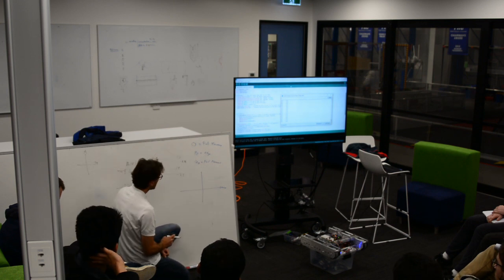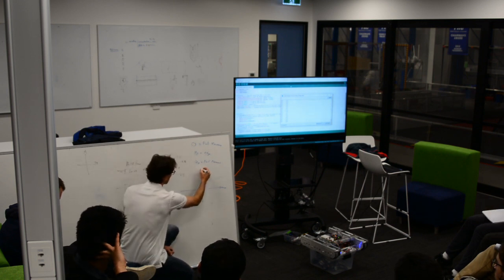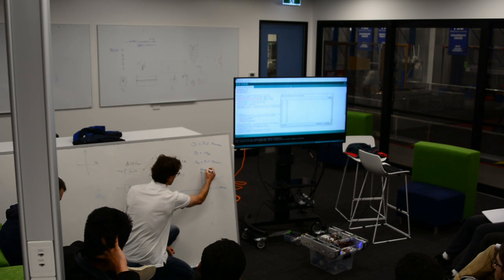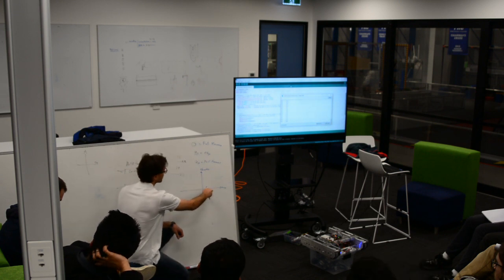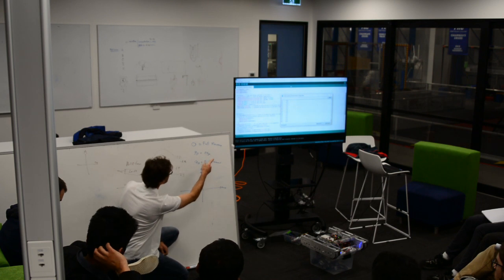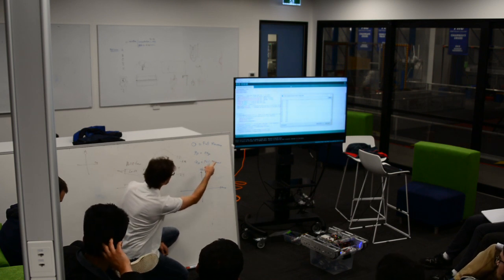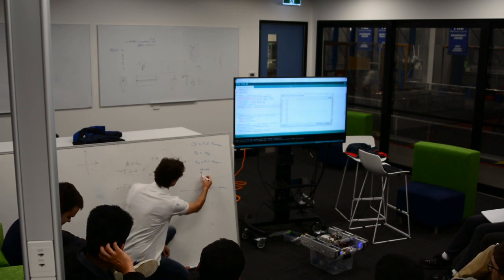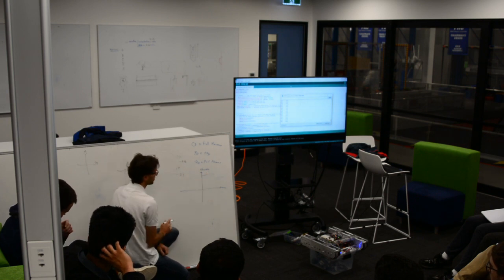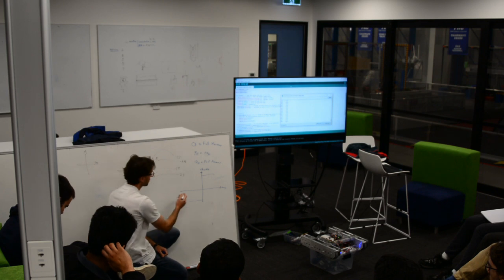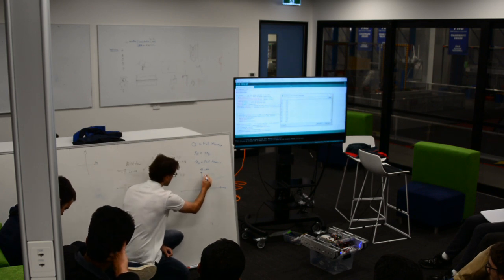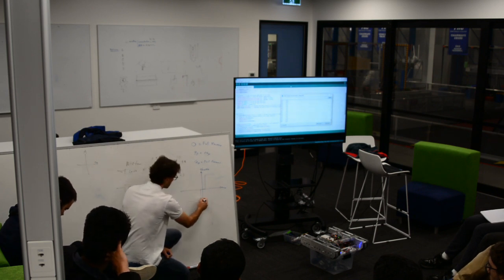Let's call this our error signal, right? And that error signal is target position minus count. Okay. And we'll call this throttle. And I'm just going to go back to a sensible throttle of +1 and -1. And we've just had, if the error is positive, then we go forward. Although you could think of the signs as being negative, and so that was what we started with, right?